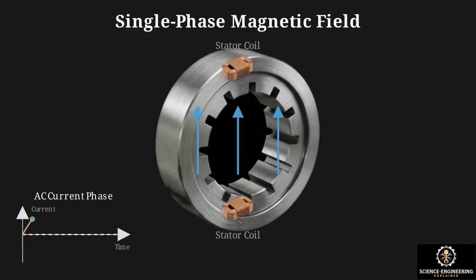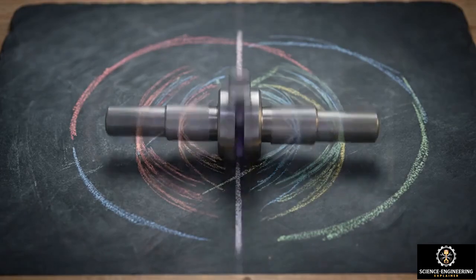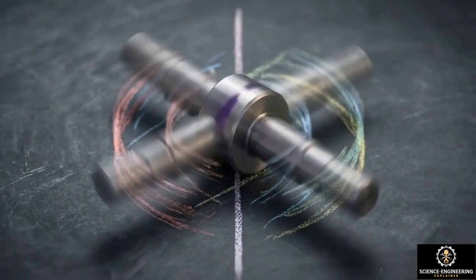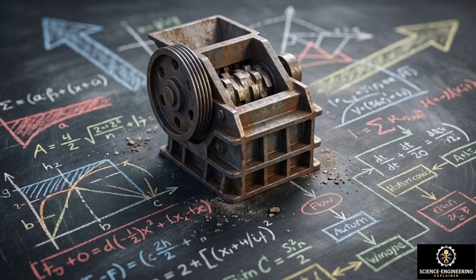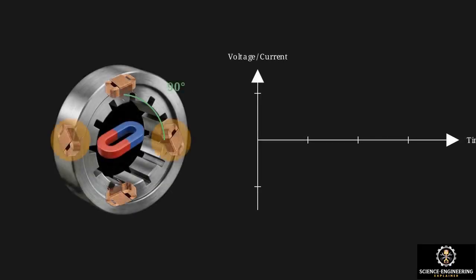A single-phase magnetic field does not rotate. It only flips polarity back and forth. If you supply this current to an induction motor, the rotor receives no directional push and will simply vibrate in place. This makes a single-phase system incapable of self-starting large industrial loads or providing the constant mechanical torque needed for heavy machinery. Engineers addressed this by adding a second set of coils to the stator, physically offset by 90 degrees.